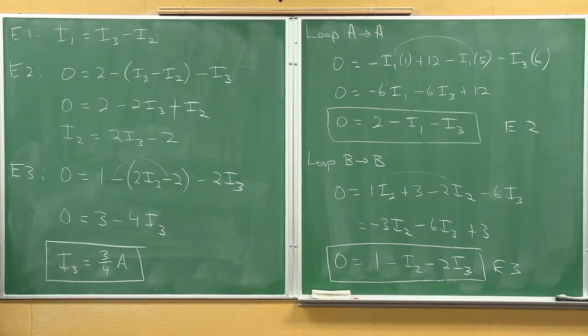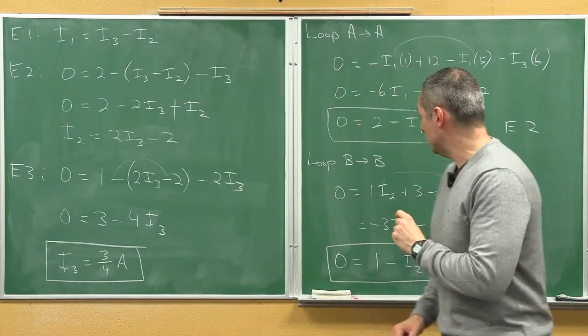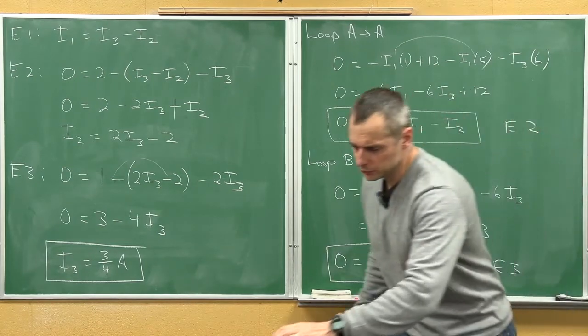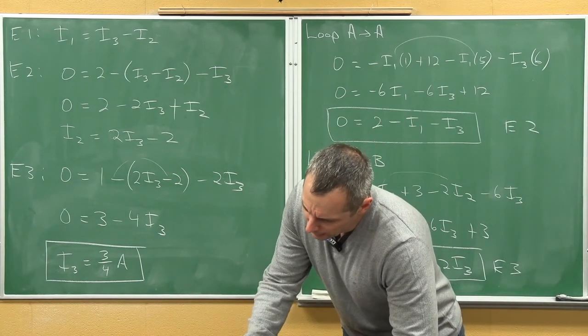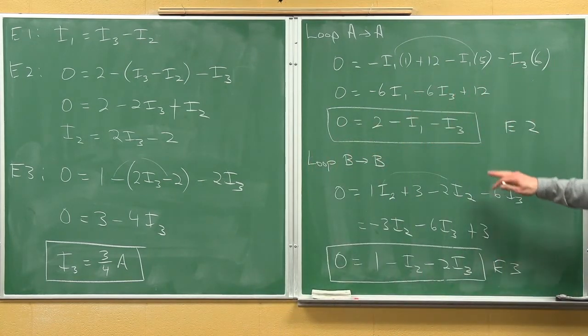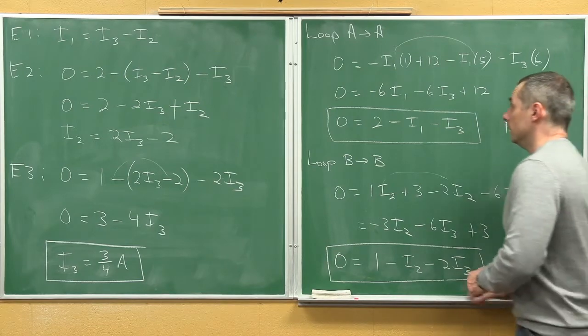There, finally, got one of the currents. Now, once we have that, we can look for an equation we could plug that into to solve for another current. Like, for example, let me see, I've got to look back at the picture. Let's go for I1. So with I3, I could find this using equation 2.